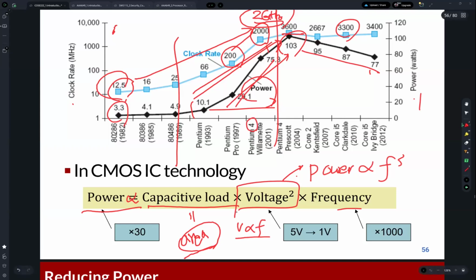Let us assume that 3 GHz is the recommended clock frequency. We can increase the clock frequency of a CPU, but in order to do that, we need to supply higher voltage. This is the basic approach of overclocking. The benefit of overclocking is that we can increase the performance of the CPU without purchasing a new CPU, right? But that's the problem.